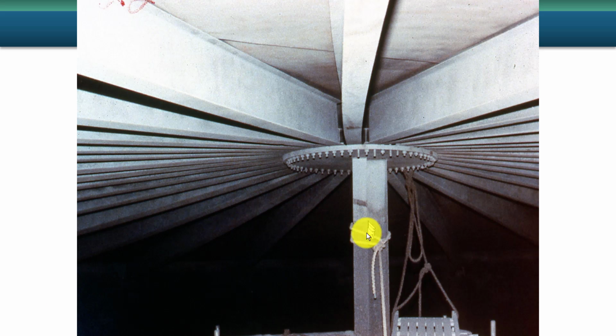The center column here is made of two channels welded together. You can see that the roof has moved a little bit. It's off center, and these rafters support the roof skin up above of this cone roof or fixed roof tank. I just want to point out that the environment is good for corrosion. You have horizontal shelves where debris, rust, and moisture can collect and start corroding. You have contact between the roof and the rafters so that this forms a good spot for crevice corrosion. But it's hard to get up here to inspect.